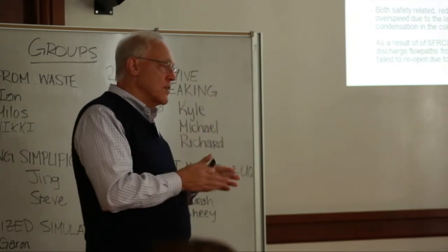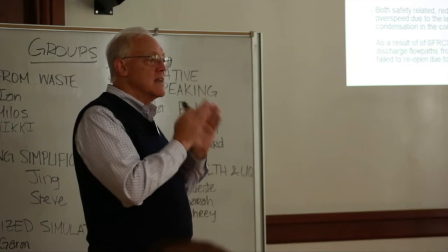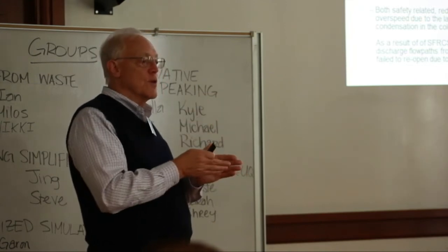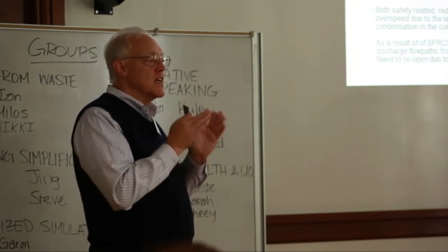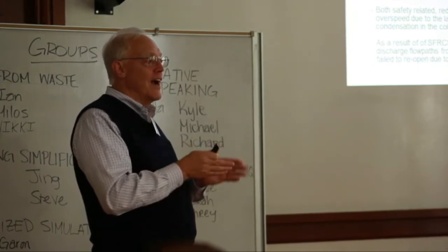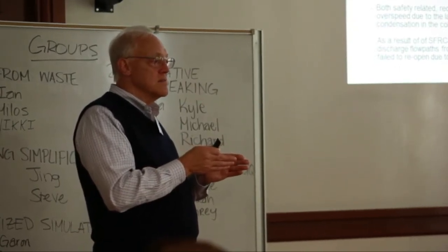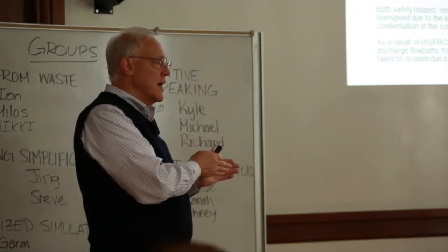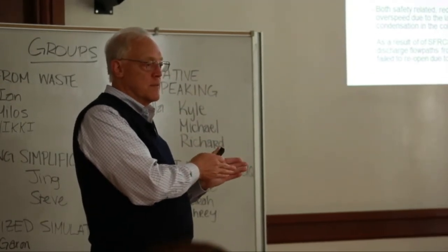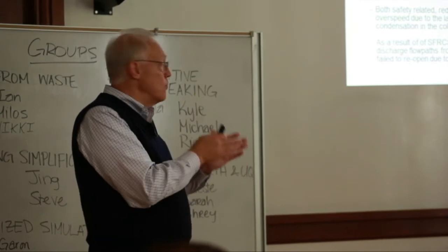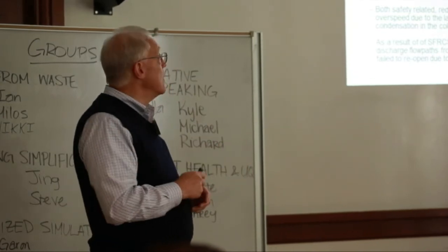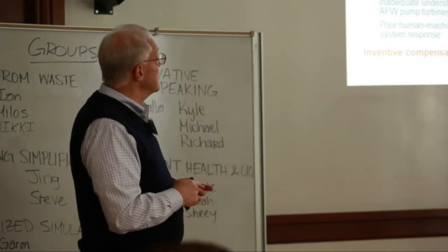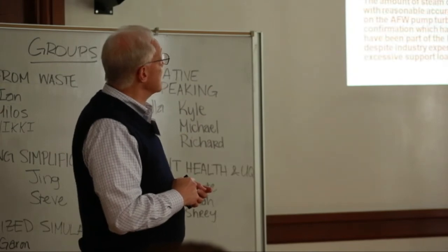Because what we had is a common cause failure. The way we were maintaining, setting up, and testing those motor operated valves, which was common across the industry worldwide, was wrong. We had a common cause failure that was so far beyond any single failure resilience thought process. Okay? We got multiple common cause failures. Now, why do I spend the time on this?